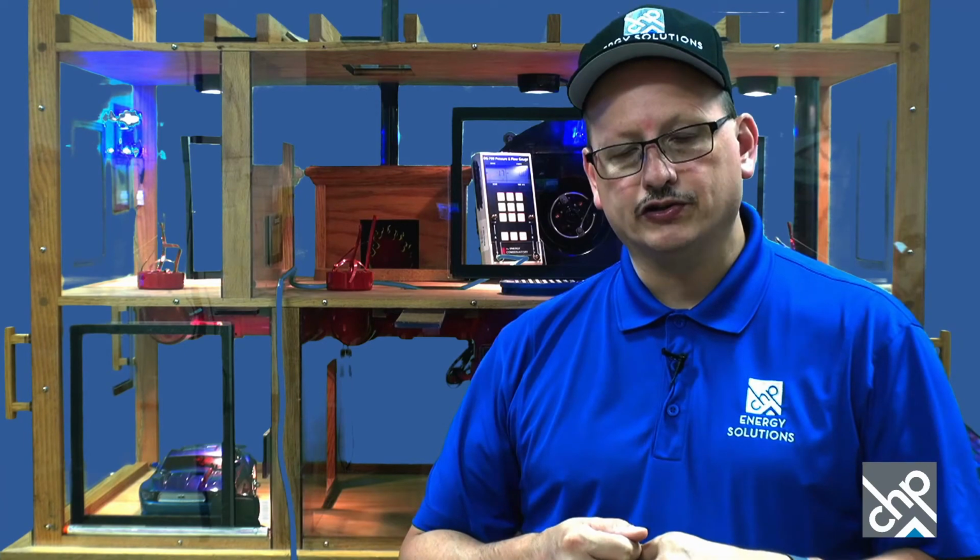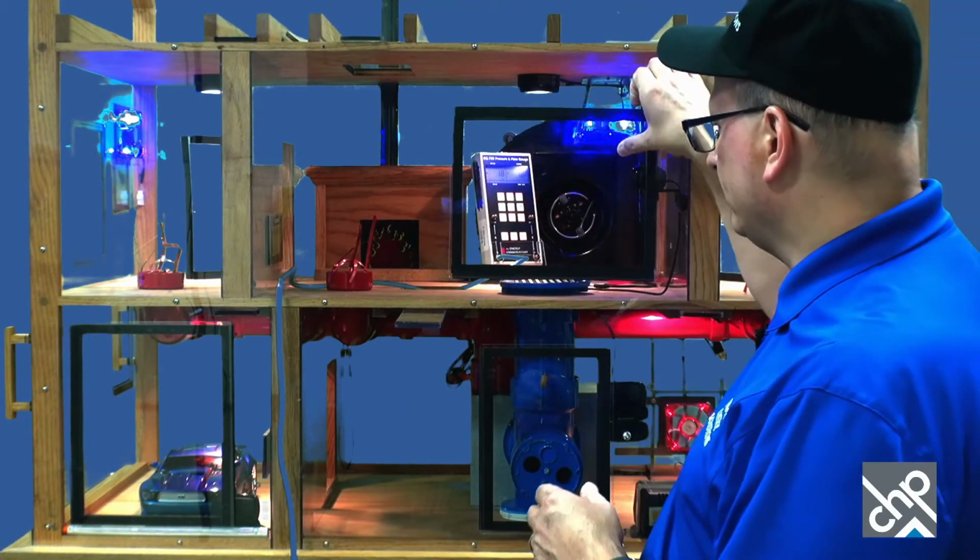Now, the next step, if you've got the exhaust fans on, is to close all the doors, basically all the interior doors. For the doors that have fans behind them, you're going to check and see if the pressure is worse with that door open or closed. A lot of times the way we do that is we take a little smoke puffer and puff smoke at the bottom of the door.